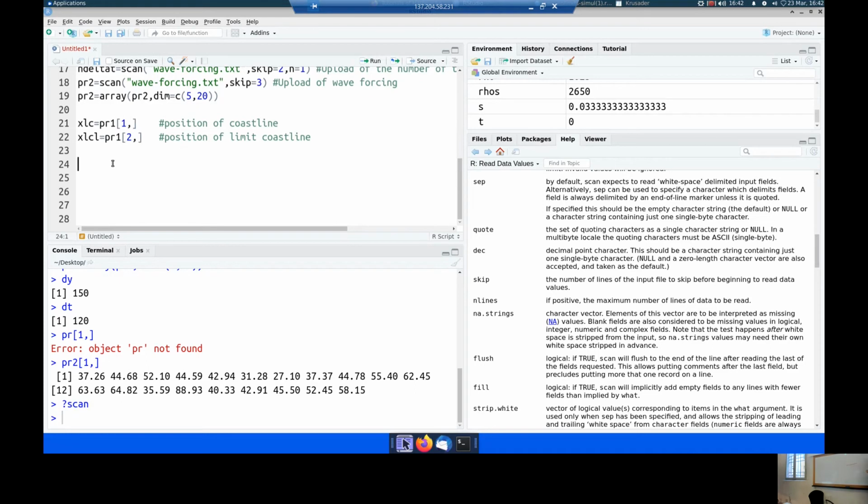So basically, you tell the program, eventually, we are not doing it here, but you can do it easily, that if you estimate in this cell here, delta xi should be less or equal than a given limiting position of the coastline. So this is the max erosion that you may have. Which means that if you here compute a sediment transport that is greater than this potential, you have to deliver to the adjacent cell only this amount.